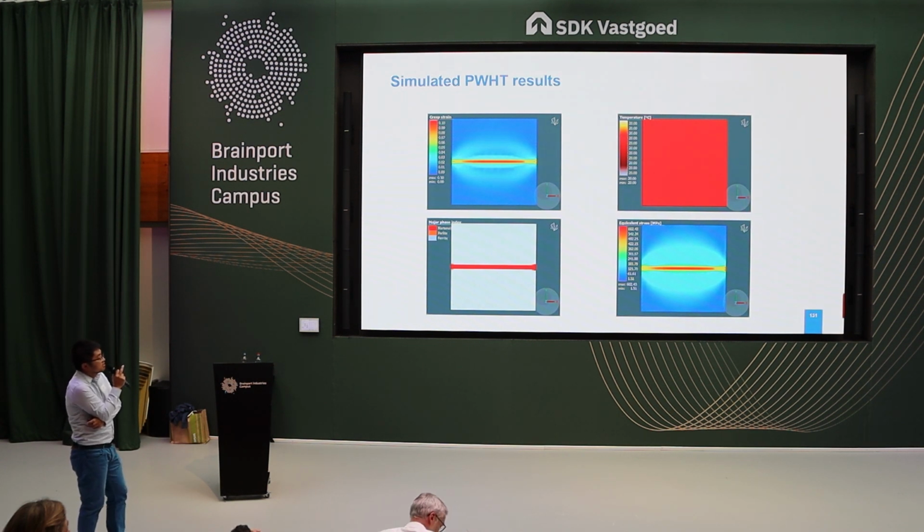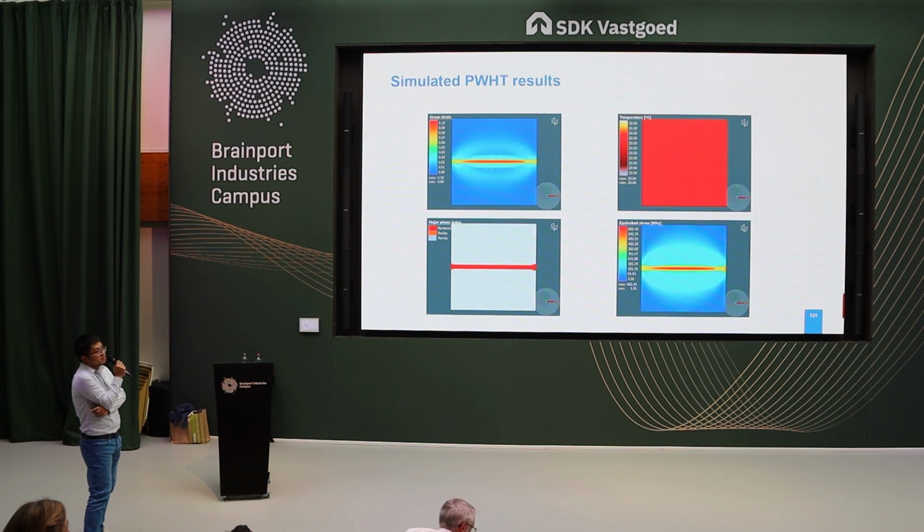Because our target temperature for the heat treatment is 500, it won't involve any microstructure change. That is also proven in the third image. And for the fourth image, we can see that after the post-weld heat treatment, the stress is released and also more homogenized and redistributed.